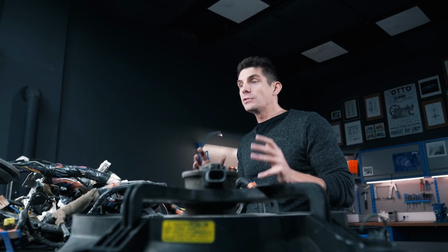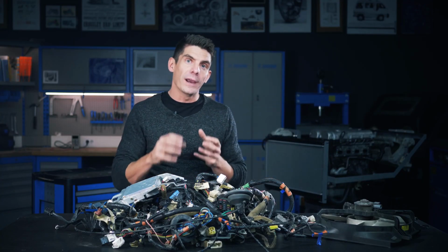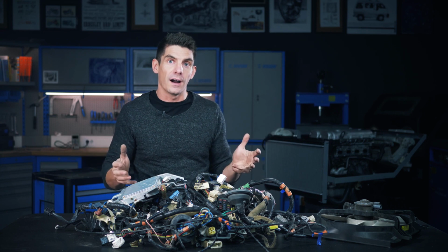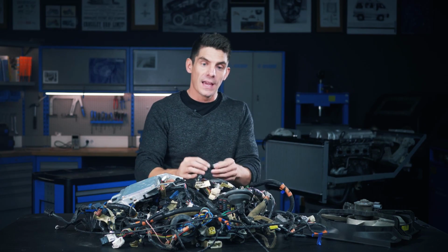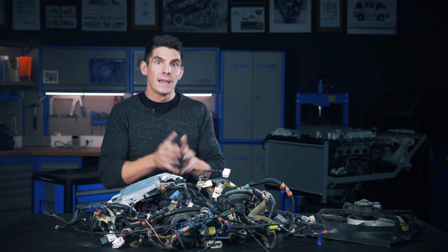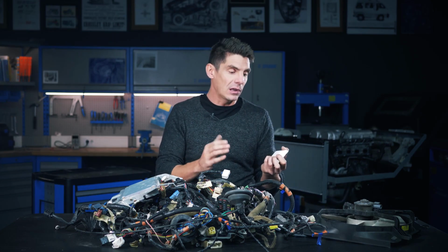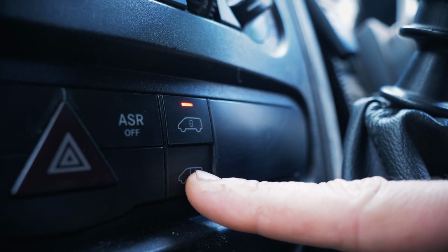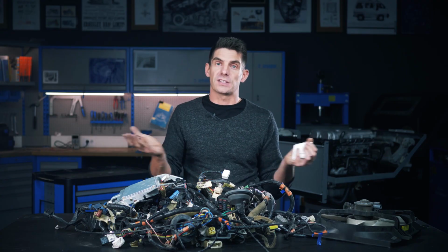Now, today, using relays is essential for electronic reasons, but even before electronics were scattered all over the car, relays were used because they allowed engineers to use thinner wires and smaller switches, and those are both lighter and cheaper. And aside from electronically controlled relays, there'll often be a relay where a mechanical switch is too small to handle the load. So maybe you've got a very delicate little switch on the dashboard handling a massive load somewhere in the car, a powerful accessory.